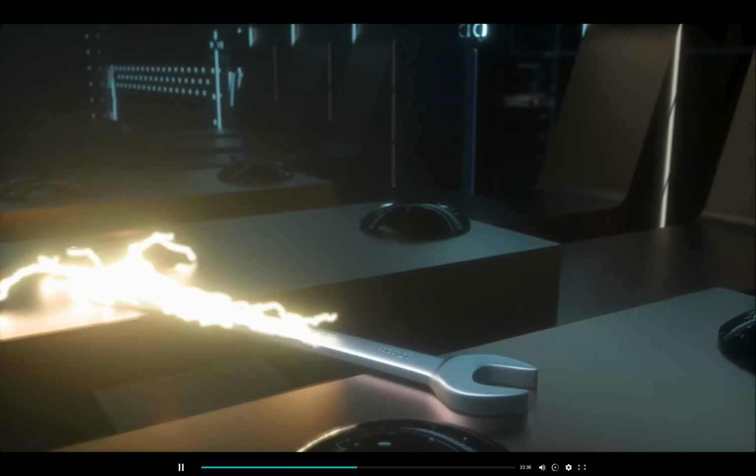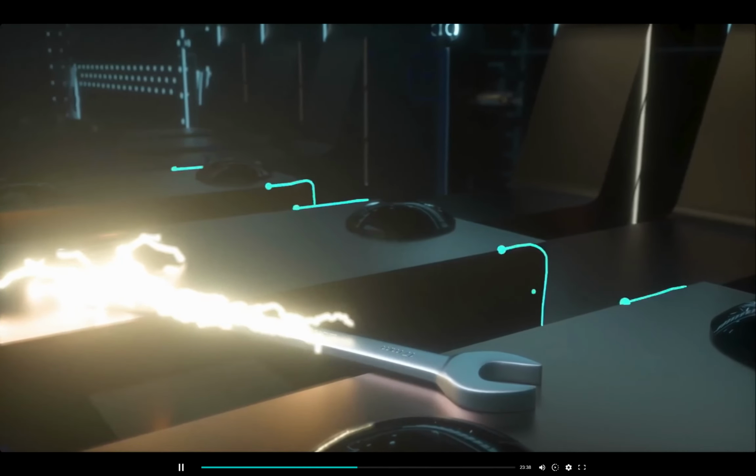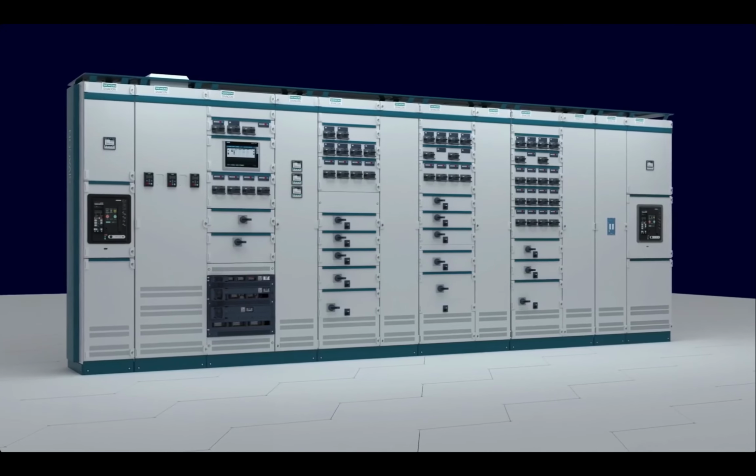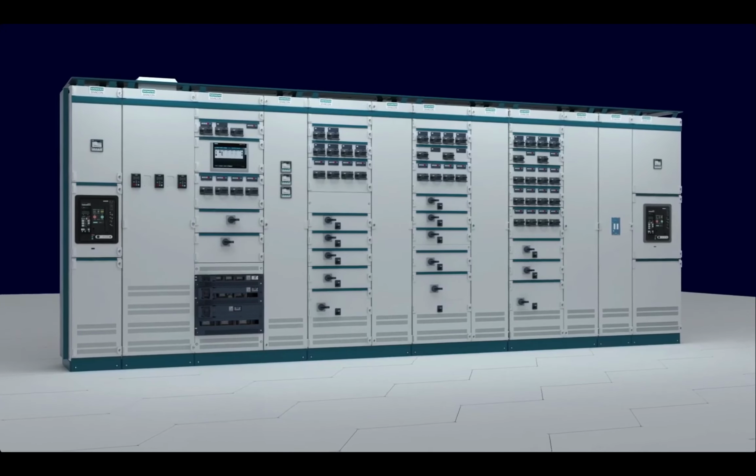In such a case, if you have an arrangement, current flows through this reactance path here, taking the energy from the arc. If you have the star point open, this current path is maintained until the feeding circuit breaker trips, pretty low short circuit currents. In the case of a phase-to-ground fault, you can continue operation without risk of damage.